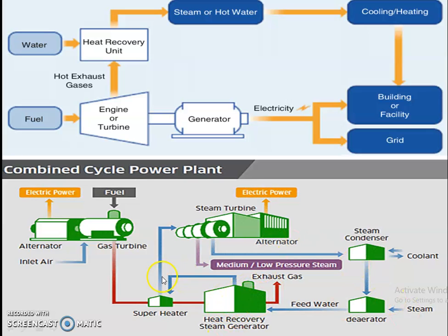After that, the low level flue gases and low level steam go to the steam turbine, again producing electricity. From the medium pressure or low pressure turbine, the exhaust steam is condensed. The condensate then goes to the deaerator or extraction superheater, and the feed water proceeds as we discussed previously in module 1.